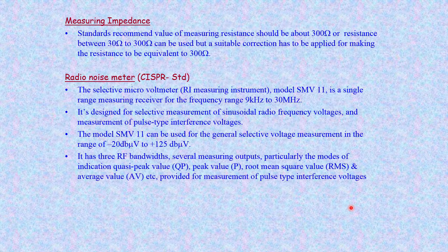The radio interference measuring unit should have various ranges for the frequencies, if required. Various modes are available for measurement, and options of measuring peak, quasi peak, and average are prescribed, so that any changes or useful information could be obtained. The radio noise meter also has to be of international standard requirement for the measurement.